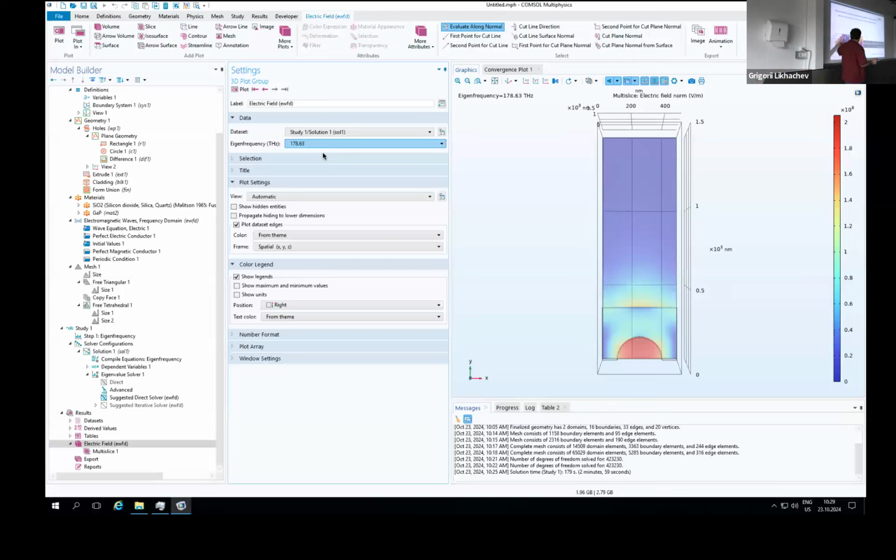And now what we do is we scan across the frequency range that we want to reflect. So we stay in a place where the band gap is large, but we move to lower center frequencies. And this is what happened basically in this plot here. So distance into mirror, you're coming inside with a frequency like 200. You get here the band gap, it goes back, right? But for 180, it will get all the way here. So the cavity is longer. So that's why we move the band gap downwards.